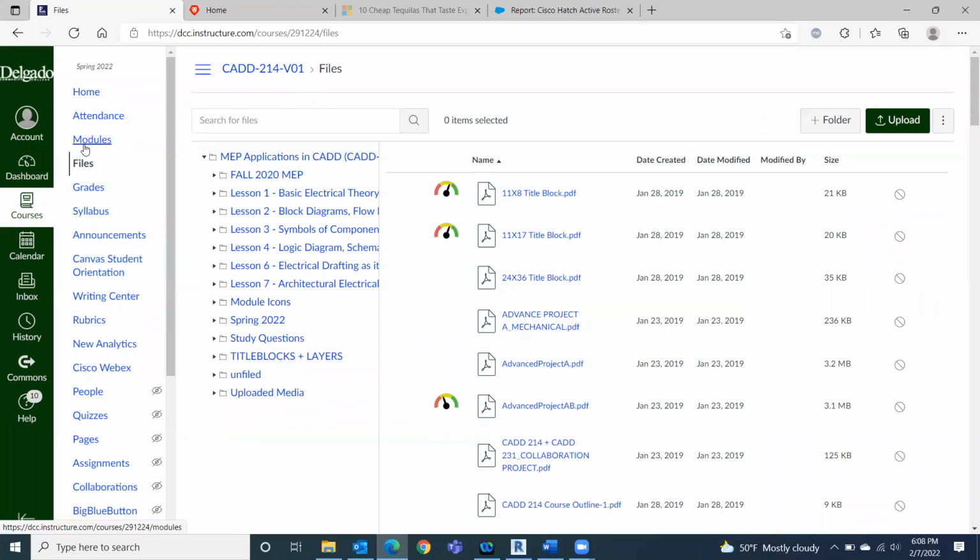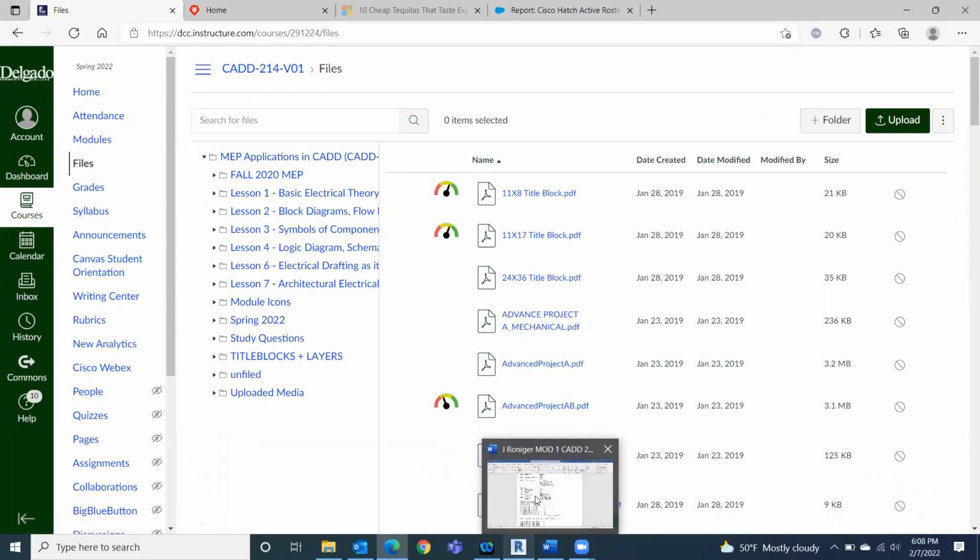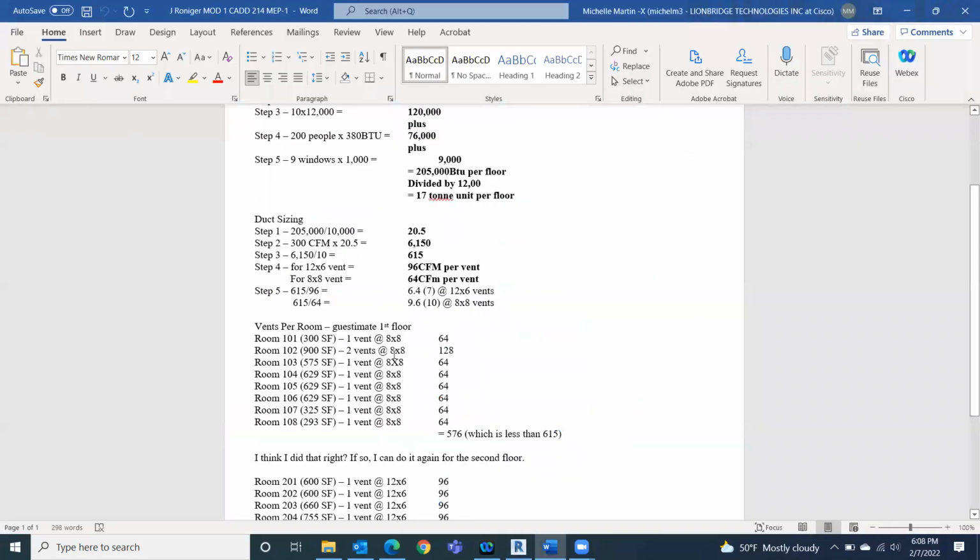My bad. No problem. So is that right? So the duct per room, like the two different duct sizes that you asked us to use, does all that look right to you? It does. But remember that these are 8x8 size ducts, and then you compare those to the size of the room that you have. These are actually really small rooms. I mean, 5,000 square foot sounds like a lot, but a lot of these are really small rooms, so they are breaking down into the correct amount.